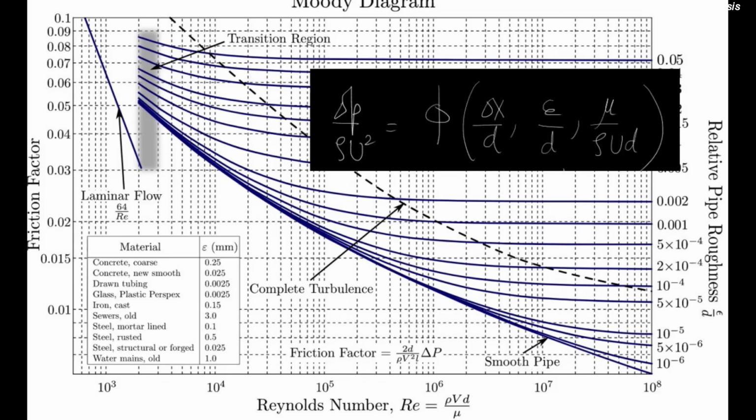So, for example, dimensionless delta p depends linearly on the length of the pipe, meaning pi 1 and pi 2 have to be in the numerator. It cannot be such that pi 1 is proportional to 1 upon pi 2. That will not work because the delta p cannot go down as the length of the pipe increases. So these are certain things which are driven usually by a fundamental understanding of the actual process or by means of some experiments.